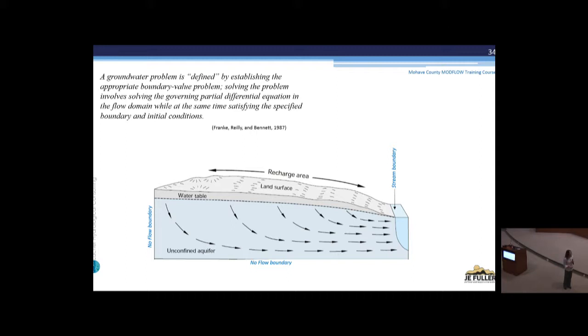But we do have to say something about how groundwater has to behave here and here. Really, the input is across the surface. So there's no behavior across these two boundaries. And groundwater flow can only flow perpendicular to lines of equal head. And I don't show that here, but if we were going to show the lines, there was a high head here and a lower head here, and if you distributed the difference in head across that, it would look something like vertical lines, vertical contours going from here to here. And these flow lines have to go perpendicular to that. They always flow perpendicular to the head gradient.